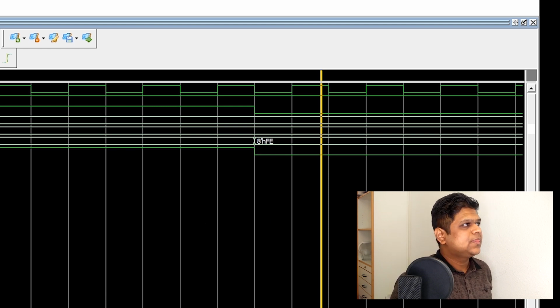So our ALU works as expected. As I said, our ALU does only add and subtract. I have not implemented add with carry, but we can do it in future. I have not yet made a video about our instruction set. In that video you will see that we have a very simple instruction set without any complicated instruction, and we don't use carry anywhere in our instruction set. I have just kept the carry output so that we can extend this CPU in the future. So maybe you can comment down your thoughts. What can we do? So this was our ALU.